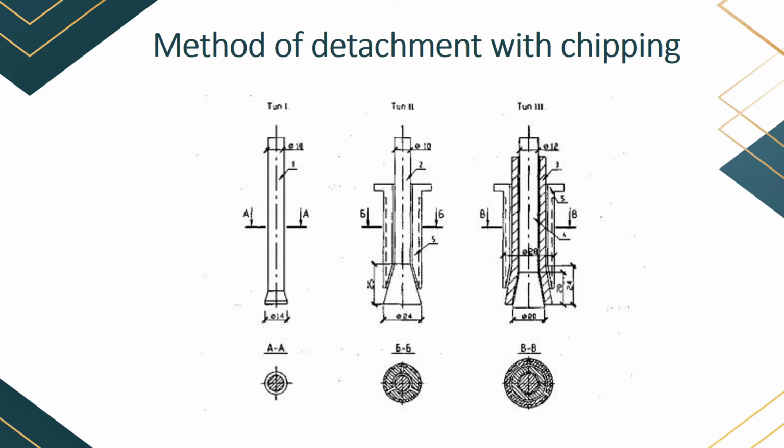In practice, in detachment, the maximum force is applied to tear off the part of the concrete surface of the structure under study. Specifically, these methods differ in the way of attaching a device to the surface of a test sample. To perform the study, a hole is made in the prepared surface of a sample. Then a special leaf type anchor of a device is inserted. A spacer is provided between the supporting studs of a device installed on the edges of a studied area of a structure, and the movable part of the device connected to the anchor inside the structure.